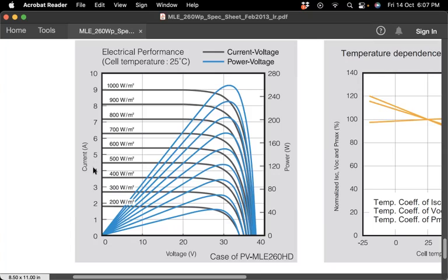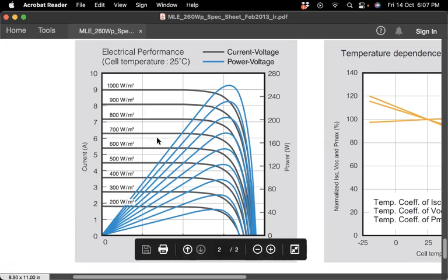Knowing that each photon converts into an electron, and current is the rate of change of electrons, the higher the number of electrons, the higher the current. So simply, the higher the number of photons, the higher the current, or the higher the intensity, the higher the current. And this is typically seen here as there is a linear proportionality between the irradiance and the current.